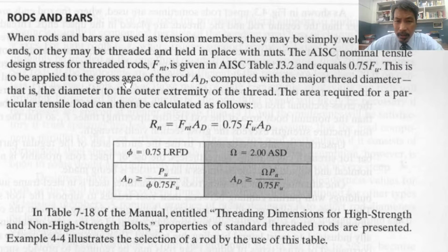Actually, not negligible. It has a maximum. It's a very great value for shear because it's a very small and lengthy cable, for example, and the shearing of that is almost impossible. So we only need to compute the material resistance using this net tension. Therefore, 0.75 is the phi, and omega is 2.